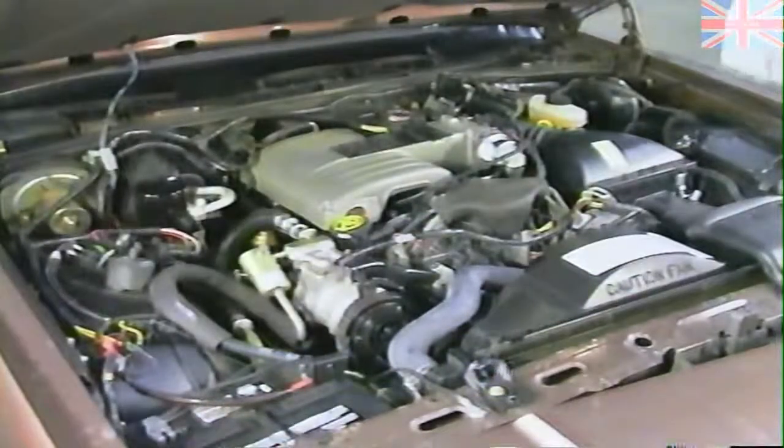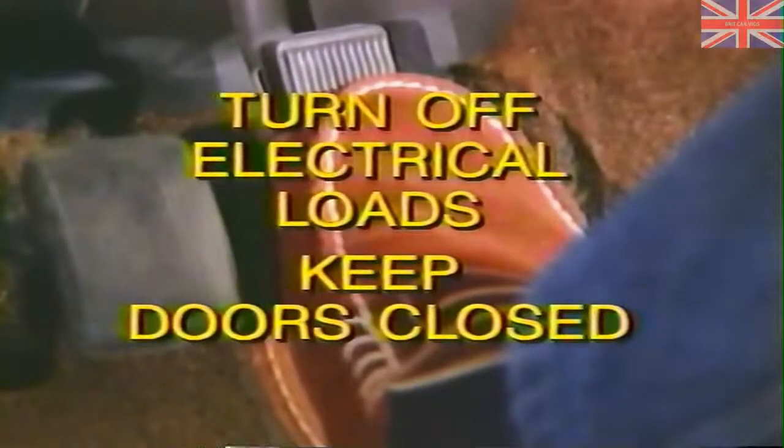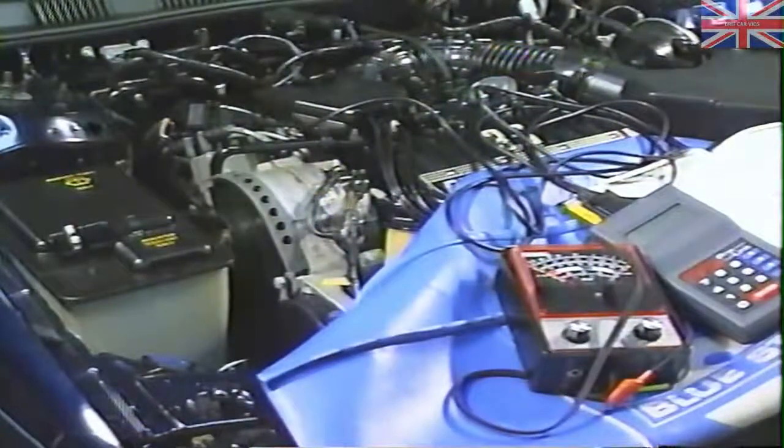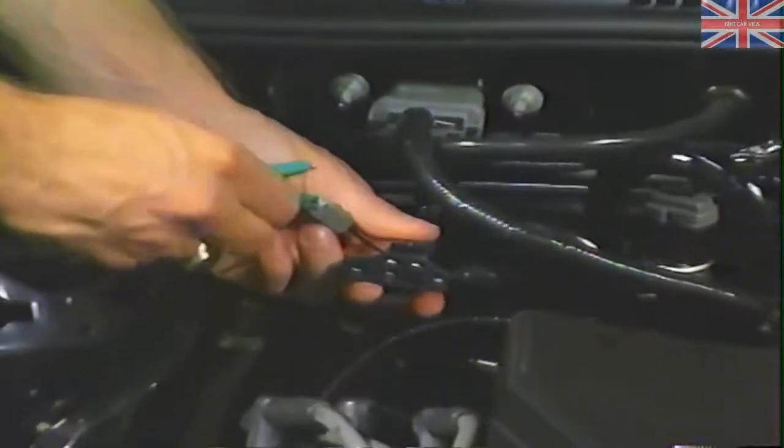The first step in properly diagnosing this vehicle is to do the visual inspection we have already completed. The second step is the actual vehicle preparation before installing test equipment. Ford recommends setting the parking brake, placing the transmission lever in park. Turn off all the electrical loads, and always make sure that the doors are kept closed. Next, run the engine until it has reached operating temperature. Turn off the engine.